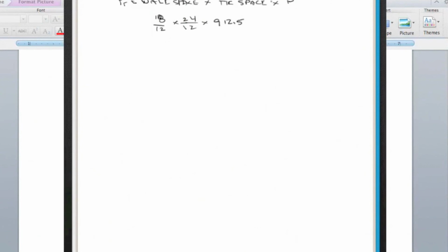So you can see that we have an area here. This is its tributary area, and this is the pressure. So doing that, we get 2737.5 pounds, which, going back to the problem statement, they were 3,500 pound capacity, so we're okay there. All right, so moving on then, let's check bearing.